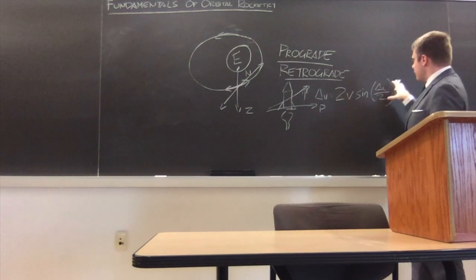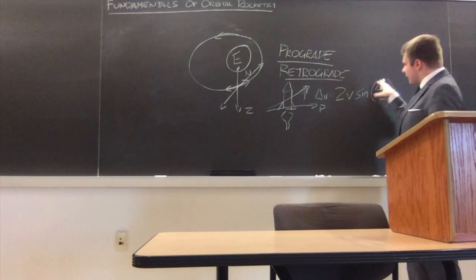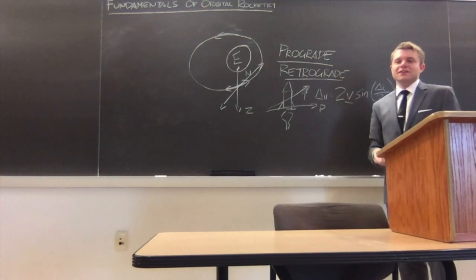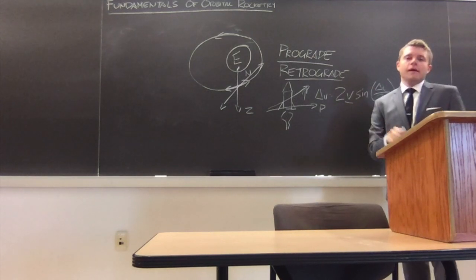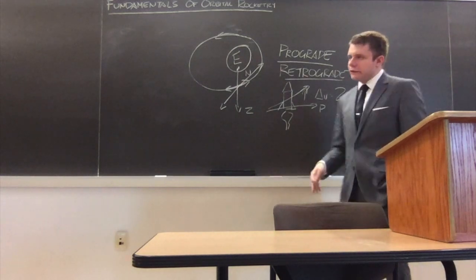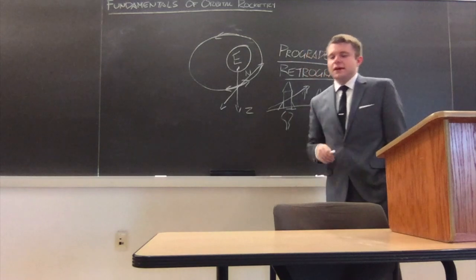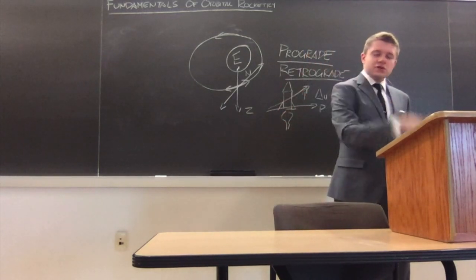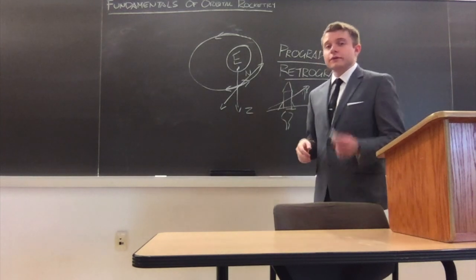You can imagine, if your inclination change is really severe, in the tens of degrees or more, it gets really big real fast, and it's a function of your velocity in your orbit, so it's a very, very large number. Generally speaking, we always try to avoid doing plane changes, which actually launches directly into the topic of launch. I'll walk you through the orbital mechanics considerations, from ignition all the way through to burnout, and that'll be a fun way to conclude this lecture.